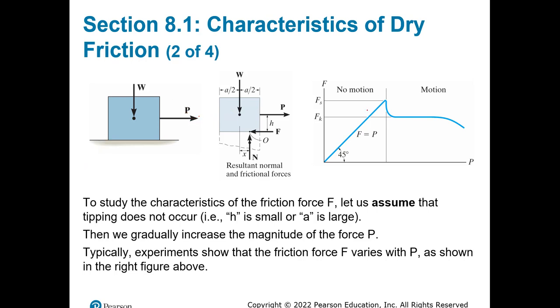As you are increasing that P, motion will not happen until you reach its maximum. As you move, you will have more P, and more P, until you reach its maximum, and then after that you will have motion. What is very important here is for you to realize that the object at the beginning will not move, and as P is applied to that object, P will need to win over the frictional force for the movement to start.